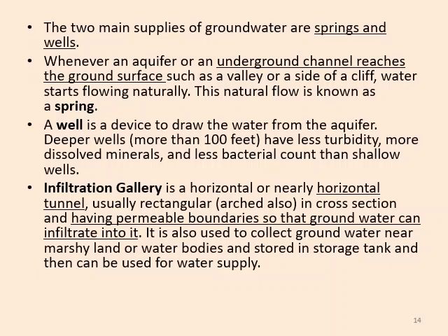Deeper wells, more than 100 feet, have less turbidity, less muddiness, more solid minerals, and less bacterial count than shallow wells. Now, an infiltration gallery is a horizontal or nearly horizontal tunnel, usually rectangular in cross section, having permeable boundaries so that groundwater can infiltrate into it.